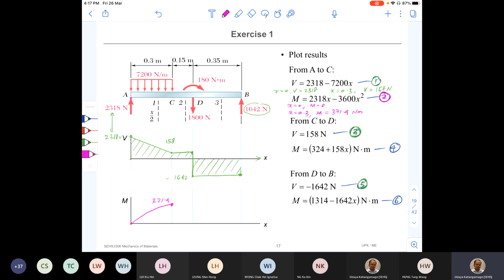So now can you see another pattern developing here? When the shear force variation is linear, or the slope is constant, the bending moment variation becomes parabolic. In other words, you can say that the function is one order higher than the shear force function. Okay, right.